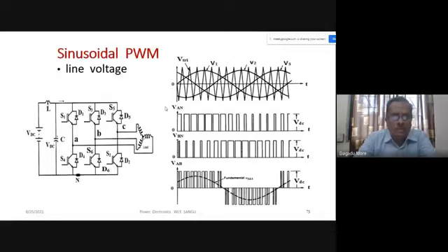Last time we discussed control of the three-phase bridge inverter and some very basic things. Three methods of controlling we have discussed. The first method is the 180 degrees mode of conduction. After that, the 120 degrees mode of conduction. These 180 and 120 degrees modes of conduction are not used in practice. In practice, we use various PWM techniques. We have listed the various PWM techniques.